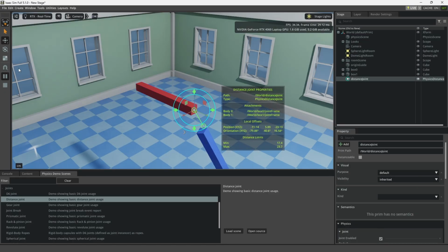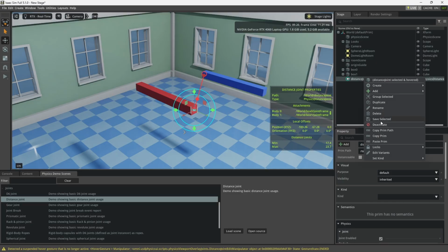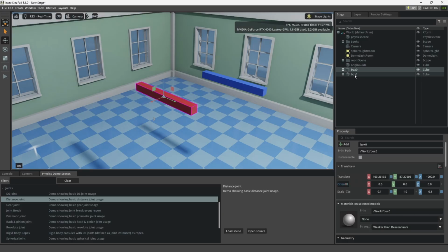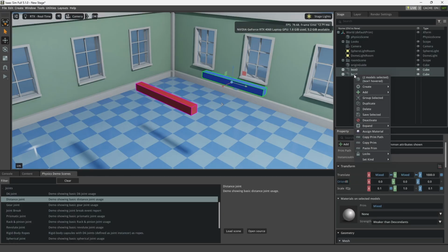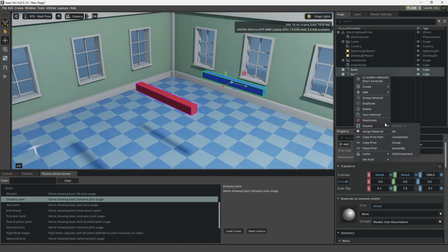Let's just go through the process of stopping this and deleting. You can see that I moved the red beam and now they're showing you the warning that you get. If I delete this, let's leave them in this weird position just to validate that. Control click on box 1, right click, validate that the position works once you've started the joint or created the joint with them in place.